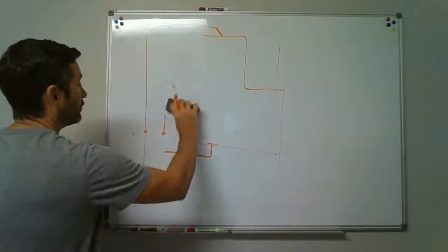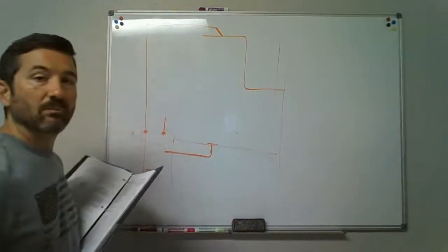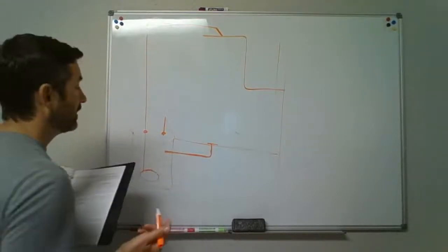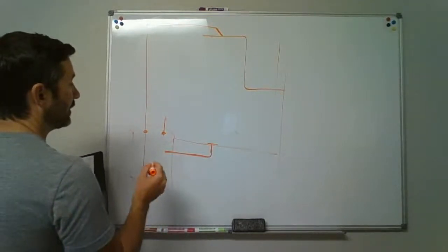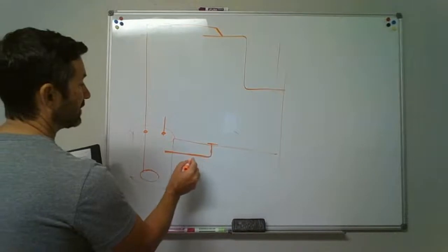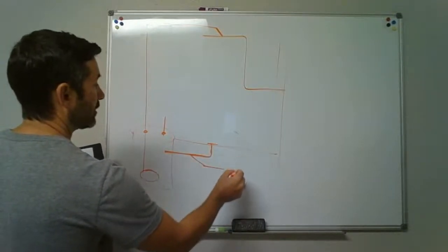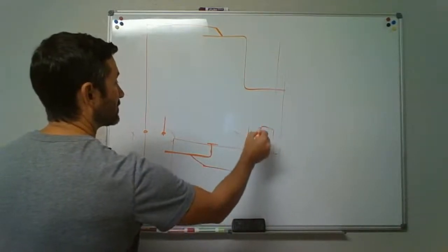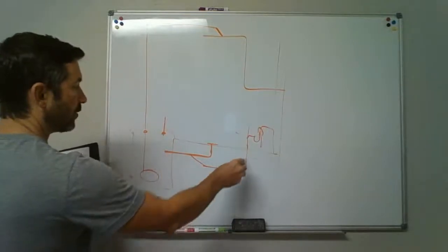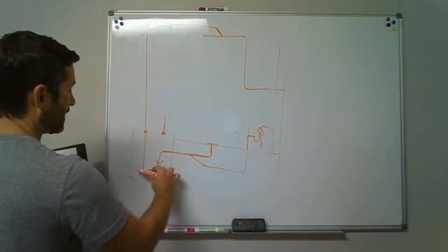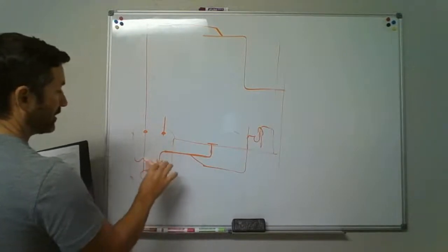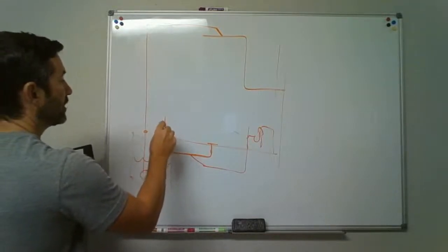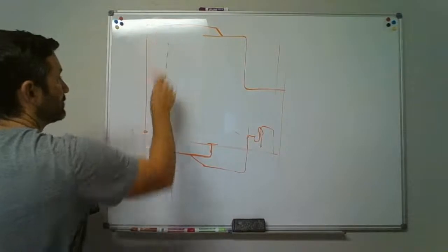And what we need is for this tank to be vented, because at times it's going to be pushing air out of the tank, and at times it's going to be drawing air into the tank, depending on what's going on. So if you've got things coming down and flowing, maybe a clothes washer tied up on this thing, with its hose hanging over, and it's draining, pumping out a lot of water. A lot of water's dumping into this tank and the water level is coming up. If this thing was full of air and here comes water gushing into it, it needs to be able to push that air out.